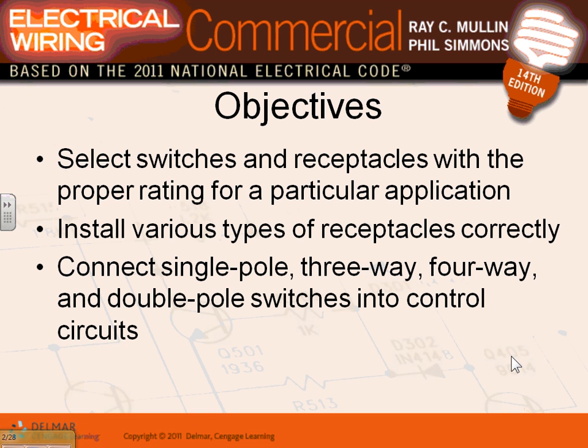How many receptacles and/or switches do I need in a commercial building? Where does it say in the building that you guys have, when you will be laying out your receptacles today, how many receptacles do I need in a cubicle? Where does it say in the code? Like in a criteria that we have from Halberg, if you remember, every cubicle on a wall is going to need a quad of 4 receptacles or 2 duplex, as well as another quad receptacle, as well as another duplex.